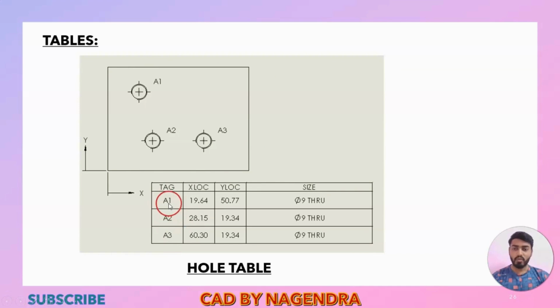Now for A1 hole, with reference to this origin point, what is the X dimension, what is the Y direction dimension, what is the diameter we want to give for that hole and what is the depth we need to give. Again for A2 hole, what is the X dimension, Y dimension, diameter and depth. Like that, however many holes we have, if we mention all in a tabular column, we will be able to read this diagram and dimension specifications properly. So this table we call a hole table. Mainly it is used for holes while we are having multiple holes.